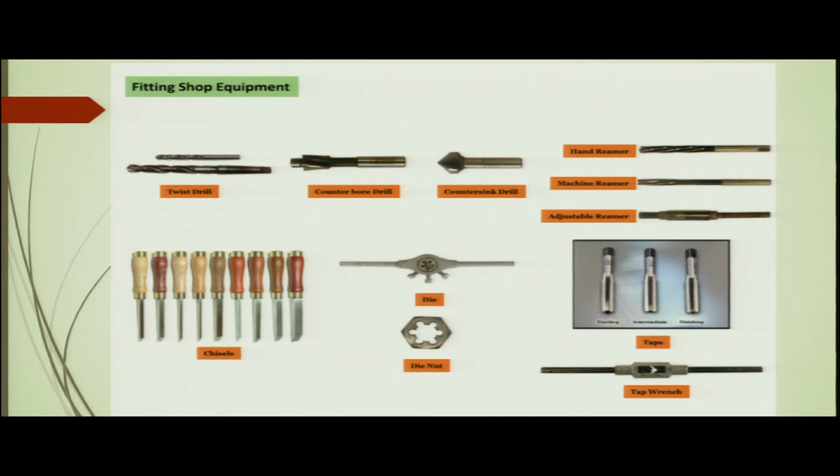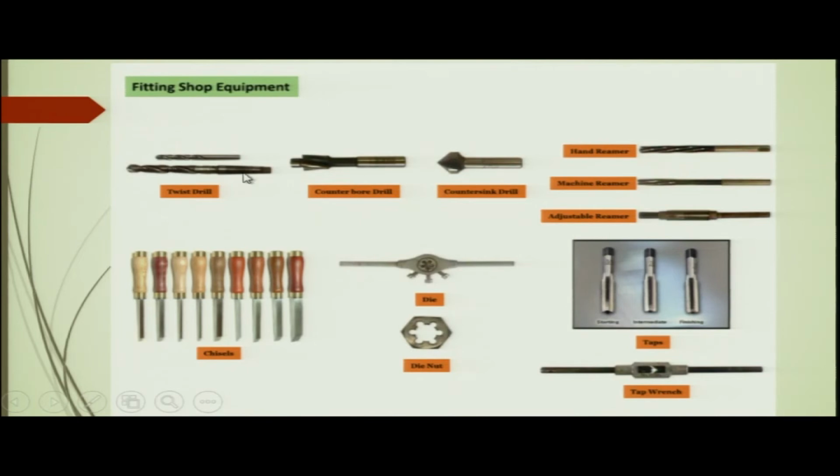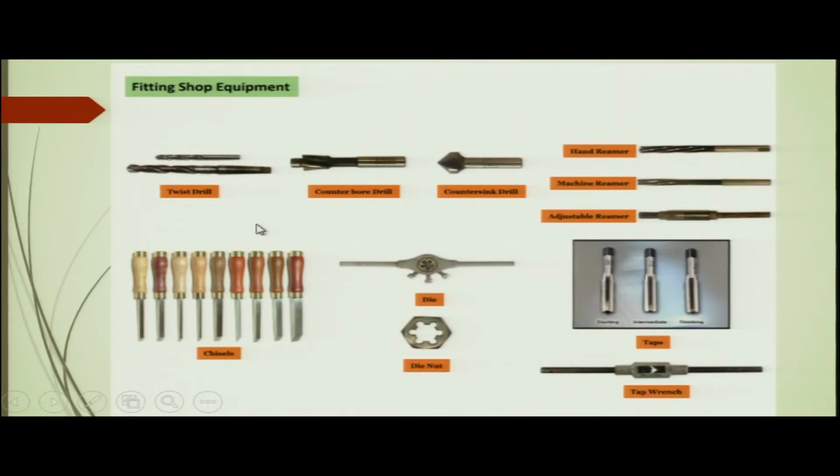That is it. There is nothing else in between this shank and the holder. There is no screw which needs to be tightened. So, when torque is transmitted from the chuck to the drill, it is only through the friction between the Morse tapers, that is the external taper of the drill and the internal taper of the drill holder or the drill chuck. In this case, the torque carrying capacity of this drill is less, because the diameter of the drill is less, so the hole drilled will not be of larger diameter. Therefore, the torque applied for drilling the hole will not be so high.